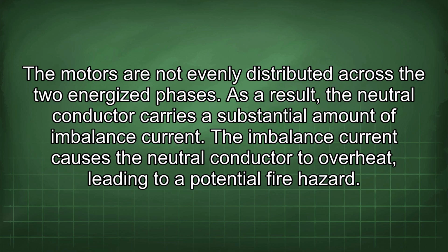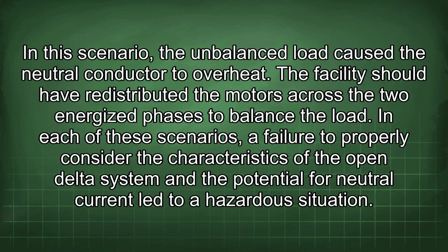As a result, the neutral conductor carries a substantial amount of imbalanced current. The imbalanced current causes the neutral conductor to overheat, leading to a potential fire hazard. In this scenario, the unbalanced load caused the neutral conductor to overheat. The facility should have redistributed the motors across the two energized phases to balance the load.